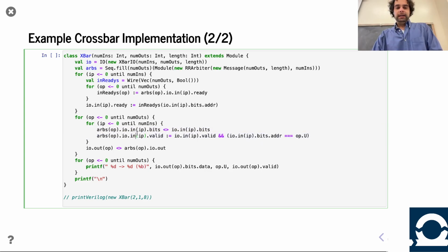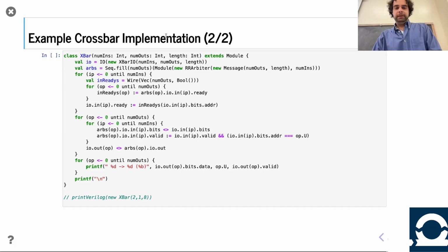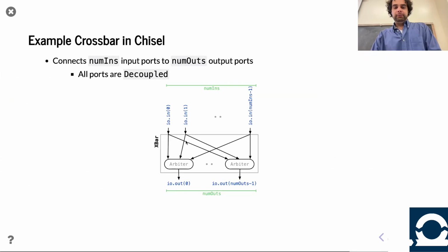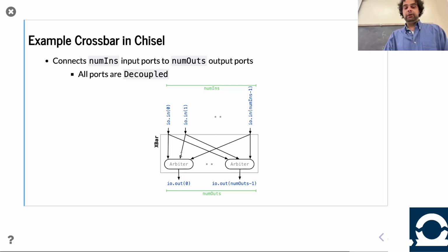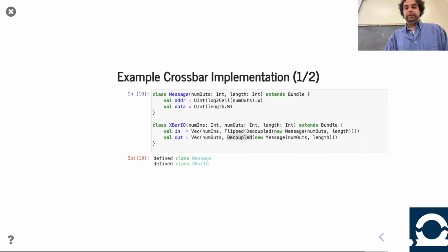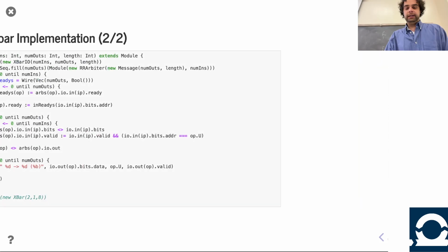We also have this interesting challenge, which wasn't shown on a diagram, but I'll talk about it anyway. This input is making a request. Remember, it's input from the point of view of the outside. It just sees a message going in. The message has an address field inside there, and it's ready valid signaling. The fact that that information is effectively broadcast to every arbiter is something inside the crossbar. And so the reality is, as an input, you actually only want one arbiter to take your request seriously, the one that you're actually requesting. So we're having that comparator basically saying, in the message, what are you requesting? And so that's what that comparator was that we were just looking at.